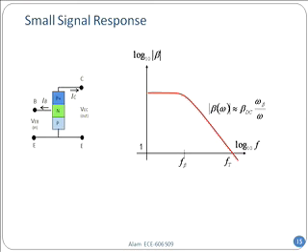So let's say, what are the cell phone signals these days? Do you know? This is about 2.4 gigahertz, right? So 2.4 gigahertz or so, that's the cell phone transmission band. So you have to design a transistor which at least amplifies comfortably up to that frequency. So your f sub beta, the point up to which things are flat, must be 2.4 in this case. If it is for some other application, then it may be lower or higher.